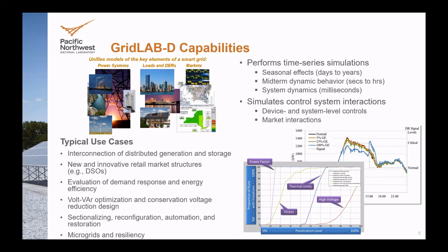That time varying behavior becomes very important because, like that demand response example earlier, if you're doing it only from a peak load scenario, you might accomplish the goal of the study, but then there's a secondary effect after you've released your curtailing event that actually causes the distribution system to be overloaded. So without capturing that time behavior, you may be missing problems that are coming out of the technology being deployed or of the particular operational procedure that you're looking at.